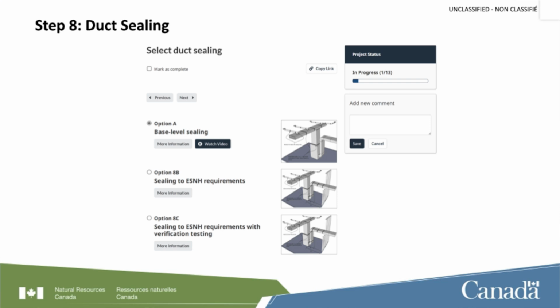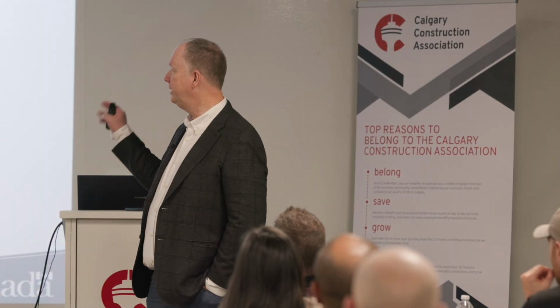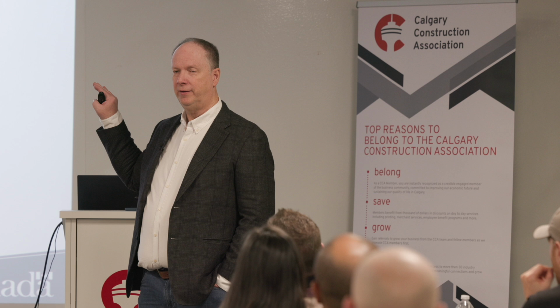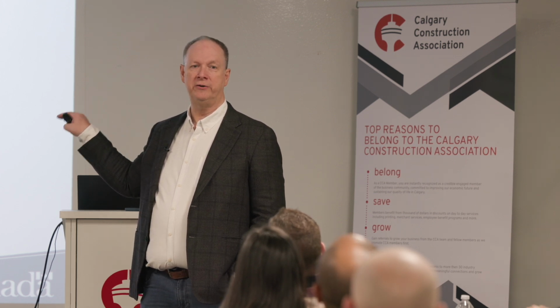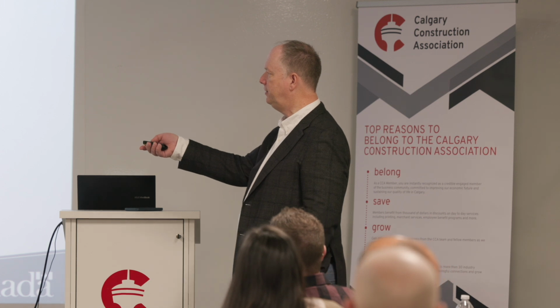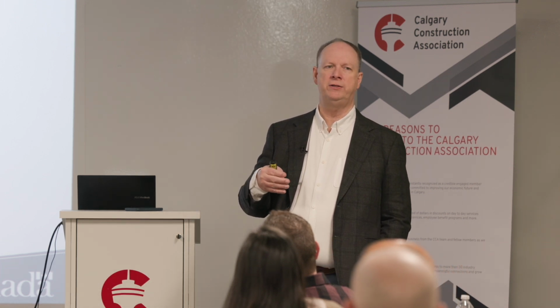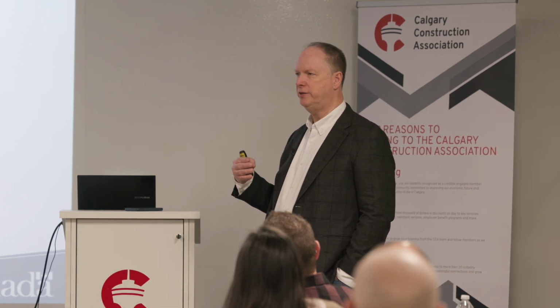So if Dave can stand on his soapbox again for a second, because I have a few HVAC contractors and builders here, please do consider a fully ducted return system. When you get into this, you can get into simplified return systems where you're not pulling cold air from every single room in the house. There are methodologies for doing that that can actually minimize the cost.